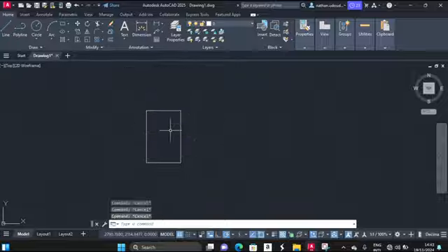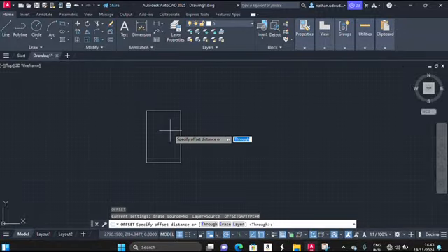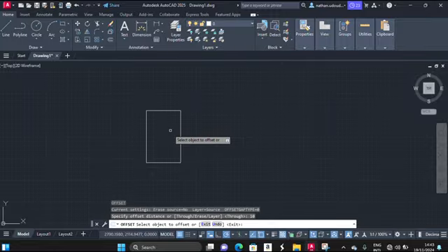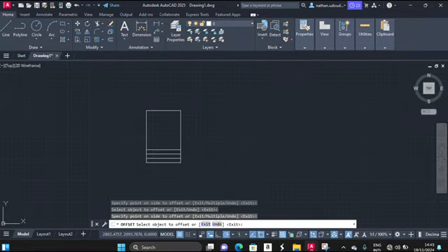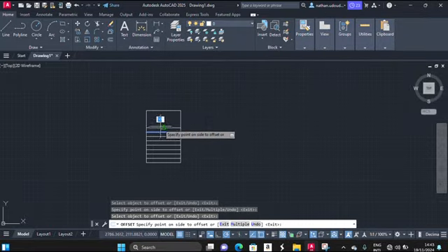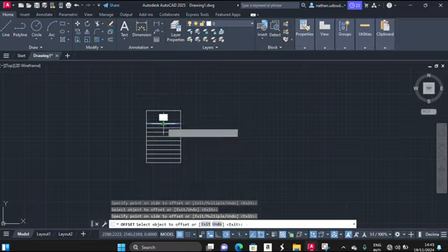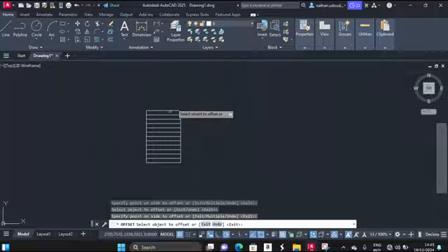So you can now offset, O, enter, enter, offset by 10. Since the pitch is 20, so 20 divided by 2 is 10. So you now offset by 10, and now you offset by 10 through the distance of 120. So now you can go to escape.